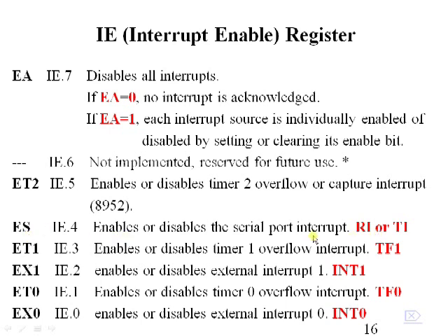So this is the RI/TI interrupt, and this is the TF1 interrupt, EX1 is the INT1 interrupt, ET0 is the TF0 interrupt, EX0 is the INT0 interrupt, and ET2 is used in the case of the 8052 controller.